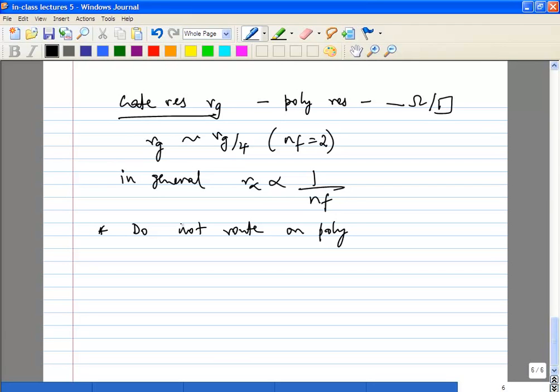Once you have thousands of gates, timing and other things become limited by the number of gates rather than the delay of each gate, and at some level you can play around with the timing at a higher level. So for standard cell gates, people do route on poly because they want to make it extremely compact. If you want to cram in a million gates and each one is just a little bit larger, it will grow quite a lot. But in analog layouts, never route on poly.